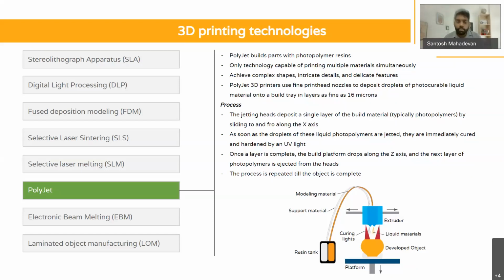So at that time, we deployed the polyjet technique to create that pitot tube and give it to them for their wind tunnel testing. And because polyjet creates parts that are equal to injection molding, they are equal to the geometry that you would expect out of a production grade part, right? Polyjet becomes very extensively used in such good applications.